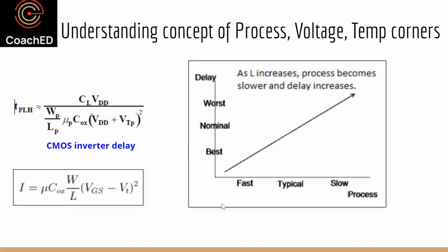So it all depends on whether you know the specs and at which PVT combination you have the worst specs, and run simulations there, and see whether the circuit delay is meeting the spec, whether the circuit leakage or dynamic power is meeting the spec at those points. That basically determines how many sims you need to run.